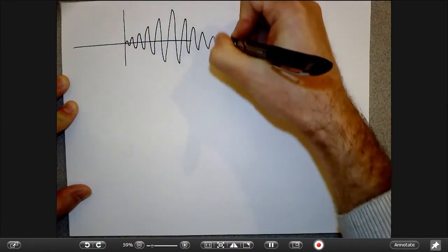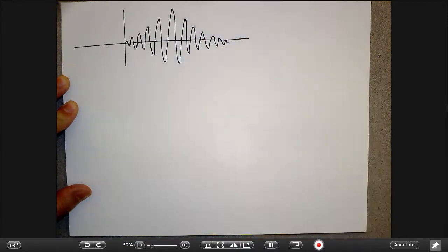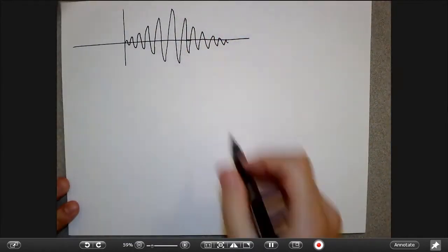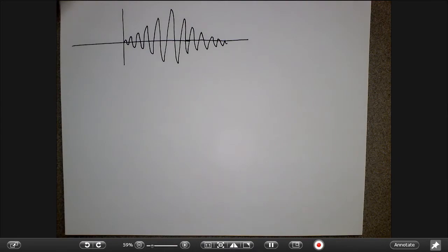So this is kind of like an AM signal in some sense, right? So this is like a carrier wave that is modulated by some sort of envelope, right? Even though there's really only fundamentally one frequency inside that signal, a Fourier analysis is going to take definitely more than one coefficient to be able to represent that signal properly, right?